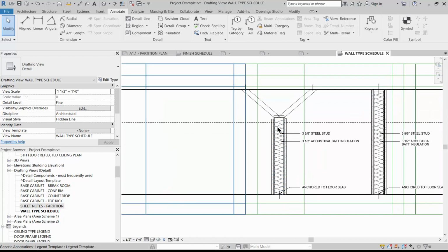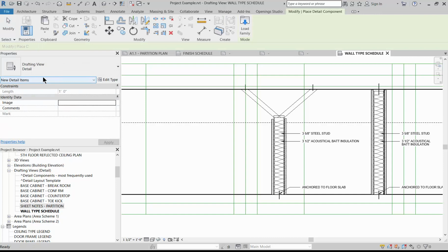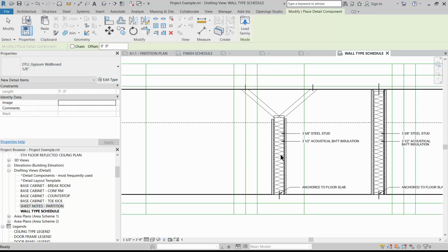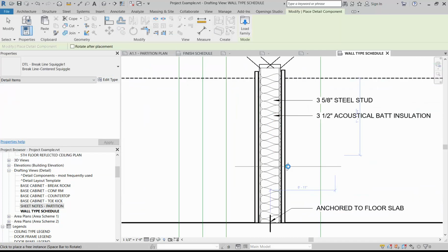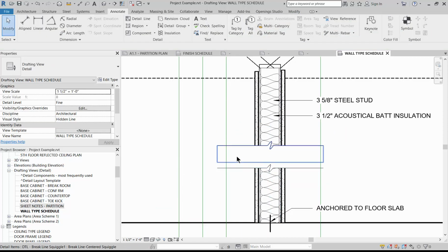Last thing, as I mentioned, this is not full height, it's not to scale. So we'll need to show with the break line that it's not to scale. So that's the last annotation we need. It's our detail component. So if you have a double-sided line, you can use that. Otherwise, we're going to place the break line, then tip it the opposite direction and place the other break line. So now you have a double cut line.